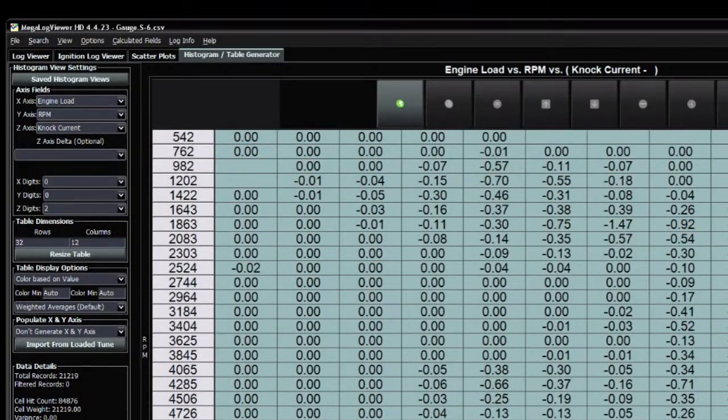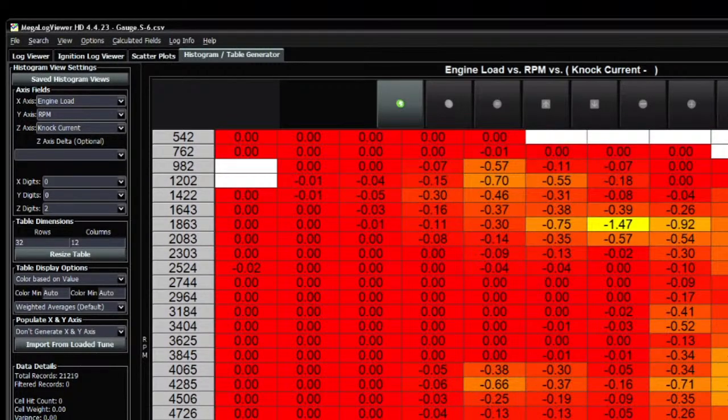So when we analyze our maps, we say, okay, we have some knocking in this area, around 5,800 RPM at this load. So there is a knock, so we either need to increase the fuel or decrease the ignition, things like this. And that's, to be honest, it. I think that's one of the greatest tools that was invented. So yeah, I want that at some point, either copied or simplified, so users are able to view the logs straight away on the website.